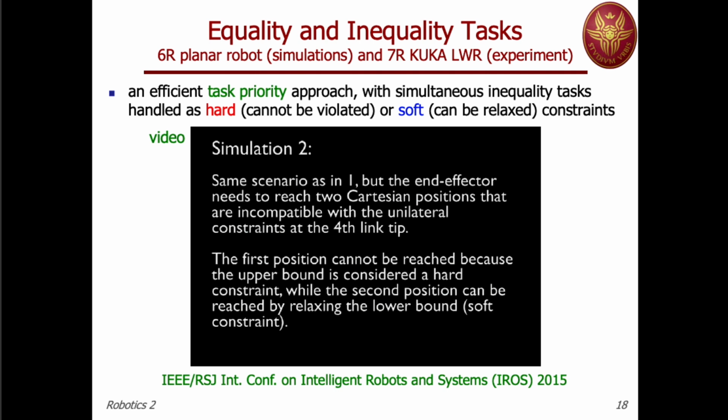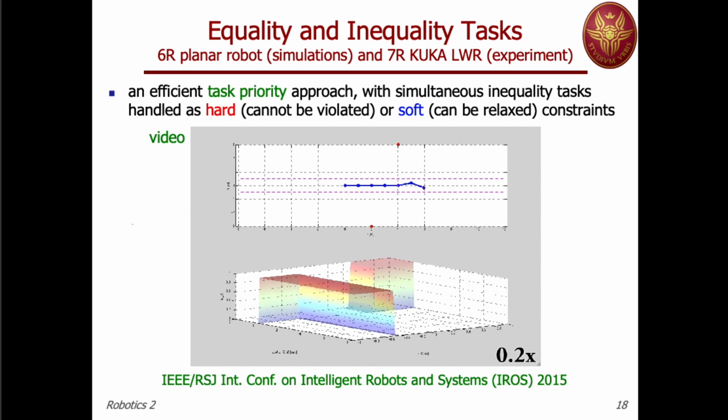Now, this second situation is a different task, point to point and then to a next point. And in the previous case, we considered the inequality constraint hard. So you see that while approaching along a straight path, because this is in fact the result of a kinematic control law, until we are in a singular configuration for the task with this constraint. So we cannot reach that point. We stretch, the error remains, and now the system is moving to the next point, which is below here.